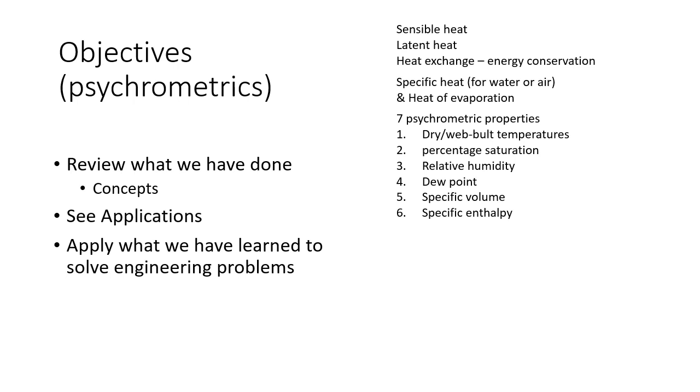Now, the other one is relative humidity. That is, again, a percentage, very similar to the saturation. They have the same value, although they have different definitions. We do not care how they are defined. But anyway, they are just 2 measures to show how much moisture is in the air, how close to the saturation.